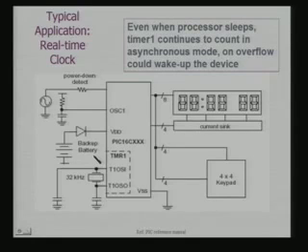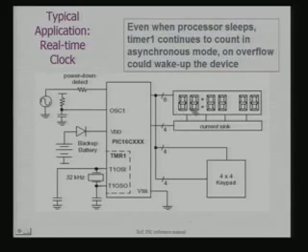Once it wakes up the processor, the processor can update the display. This is an LCD display, and many of these PIC microcontrollers do have an LCD interface module. So using that module, I can connect an LCD and update the display. The processor is not doing anything normally. It just wakes up on getting the interrupt on timer overflow, and updates the display.